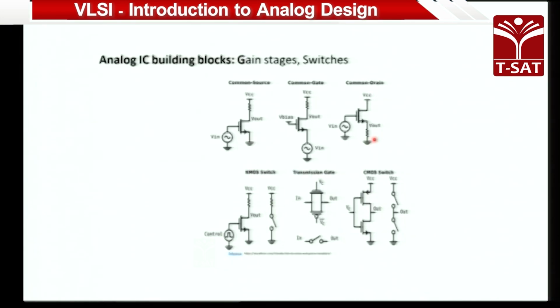And then with these two, device and circuits, you can read what these components are: what is a current mirror, what is a differential pair, and what are components like common source, common drain, common gate. These are all structures used for specific purposes. So you should know what purpose you should use each for, and what the advantages and disadvantages of these structures are.